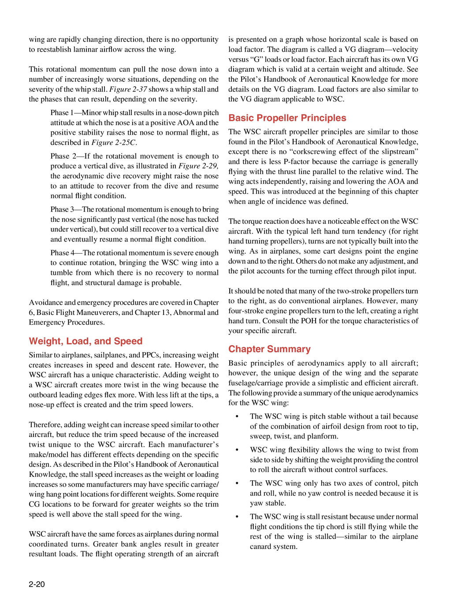Phase 2, if the rotational movement is enough to produce a vertical dive, as illustrated in Figure 229, the aerodynamic dive recovery might raise the nose to an attitude to recover from the dive and resume normal flight condition. Phase 3, the rotational momentum is enough to bring the nose significantly past vertical, the nose has tucked under vertical, but could still recover to a vertical dive and eventually resume a normal flight condition.